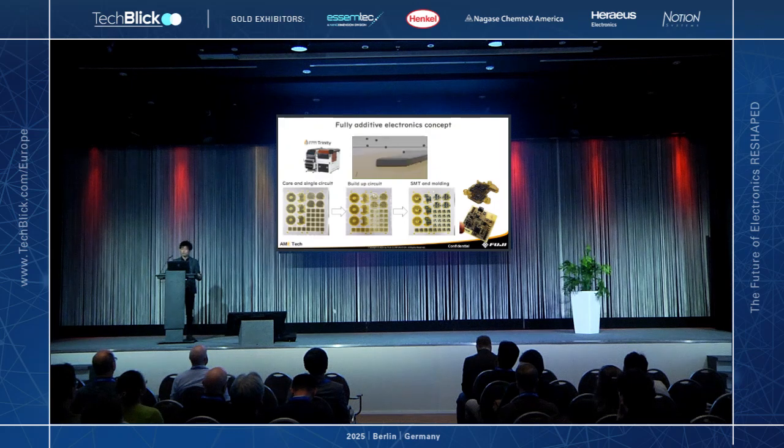And on that surface, this machine prints the silver conductive ink as well, using the same resolution of the inkjetting system. The printed silver can be dried and sintered at a very low temperature. And by repeating that process, it can make a multi-layer circuit.